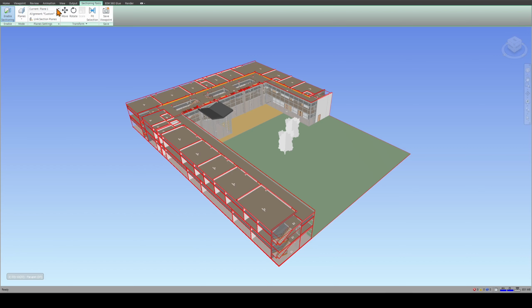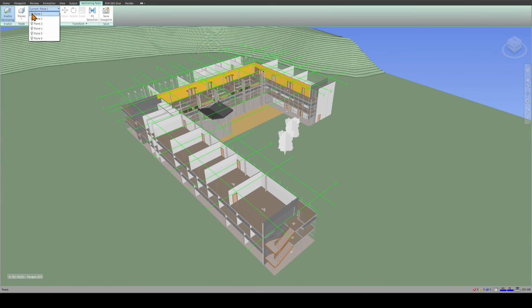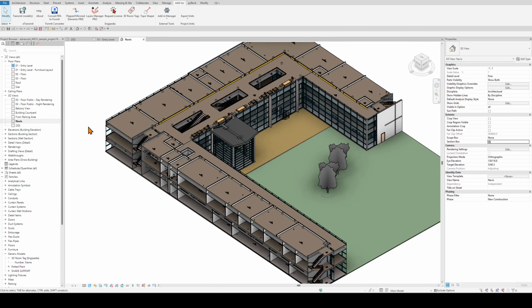But if you turn them off, you will notice that things that were not fully visible in Revit were not exported. So please be careful about that. The point I'm trying to make here is have in mind that your Navisworks model is not just cut with section planes. There are elements missing. Basically, whatever is not visible in Revit, you can consider it will not be in Navisworks.